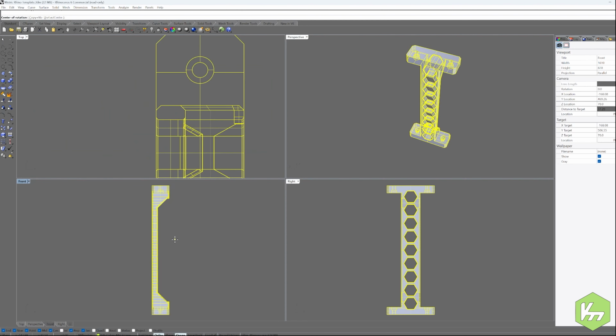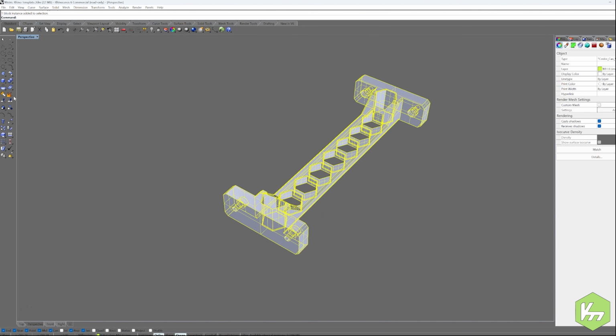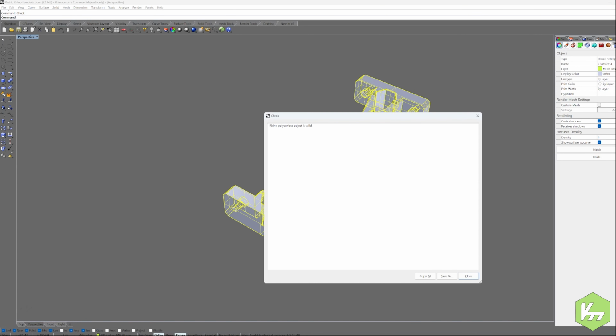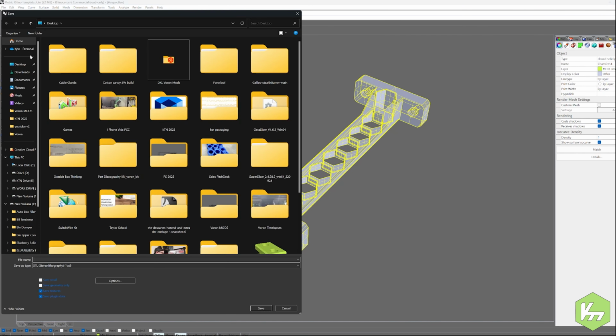We're gonna rotate the part and orient it correctly the way that it should be oriented, and look at the 3D. So if I explode the object, it says up here, exploded an instance into one object. If I do it again, surface has 232 surfaces, so we're gonna join it and then type in check, and the poly surface object is valid. Okay, so we know this is good.